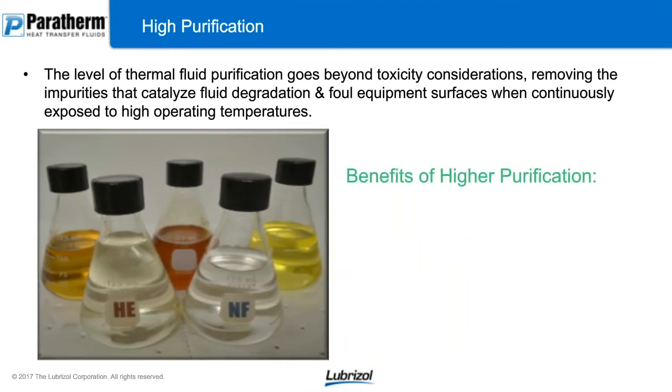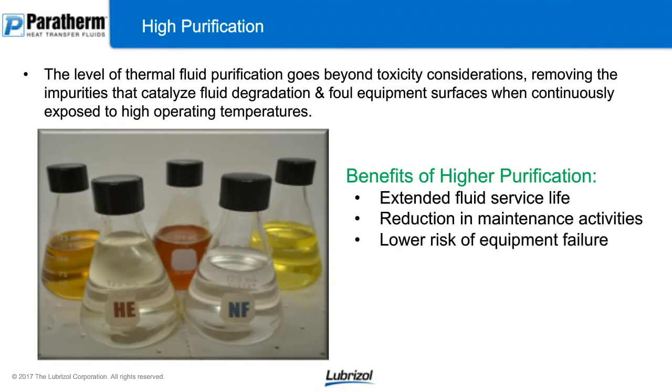So, benefits of high purification. You're going to get extended fluid service life if you have a more pure fluid. That's also going to lead to reduction in maintenance activities. Something that's not as good of a base product when you start off is going to lead to premature fouling, which is going to lead to more maintenance activities that are usually unscheduled. You'll have a lower risk of equipment failure, which ties hand in hand with the maintenance point. And you're going to have greater consistency in your performance over the lifespan of the fluid.